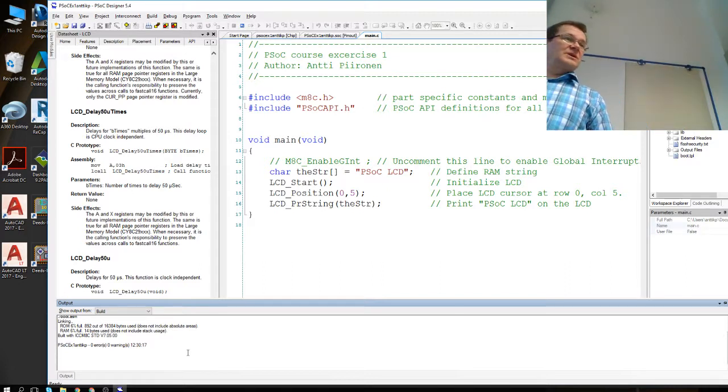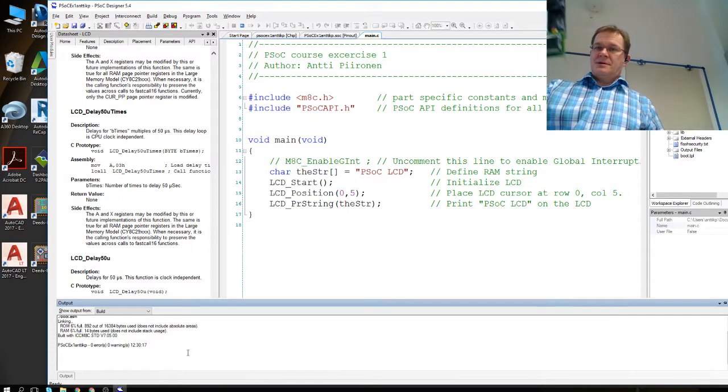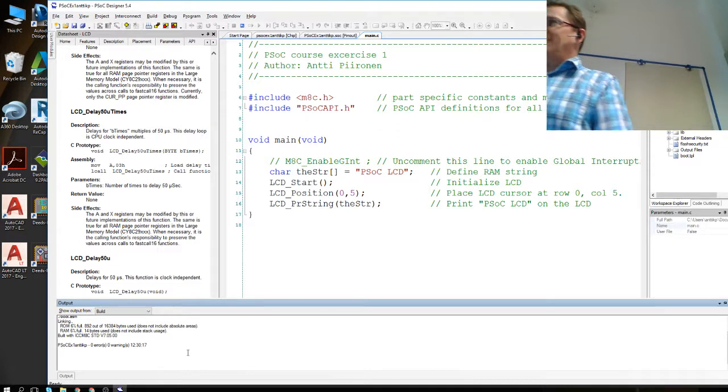And now, what we need to do on the hardware: connect the LCD. There's the connector for it. Make sure that it lines up right. It's easy to make one pin offset, and then it doesn't work anymore. So something like that. Then you would need the programmer. Mini USB. And you know what to do with the other end.